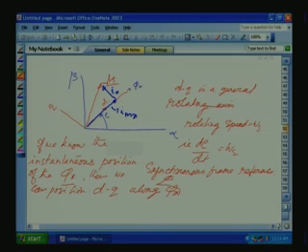By controlling the orthogonal component we can control the torque, like in a separately excited DC machine, and by keeping the current along psi r constant under all dynamic conditions, the flux will be kept constant. So, we will get a performance similar to a separately excited DC machine.